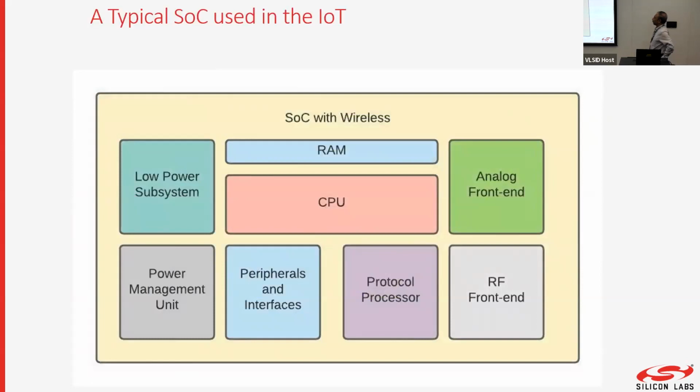All right. So when you look at the processing unit, or the MCU, I called it, which is actually an SoC or system on chip, it's got a few portions in it. We are assuming something with wireless because that's our focus of today's talk: an IoT device with wireless connectivity. We have peripherals and interfaces, which include A to D converters, digital GPIO pins. You can have I2C interfaces, SPI interfaces. All of them are there from which you can interact with the outside world.